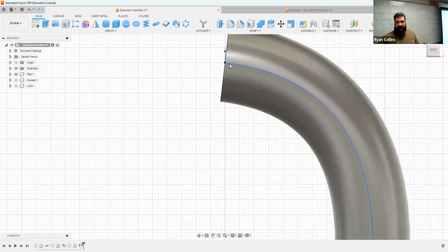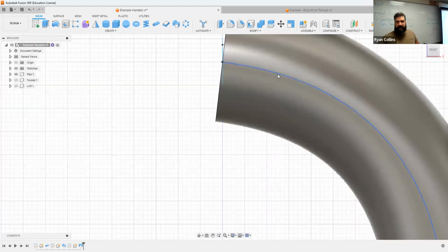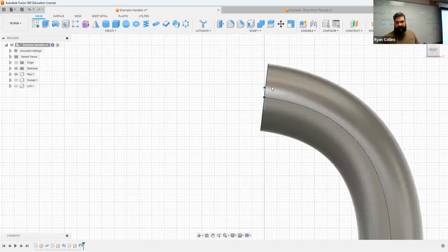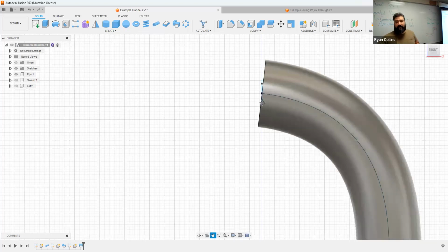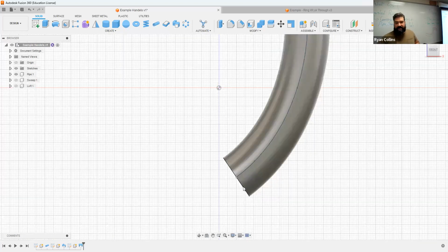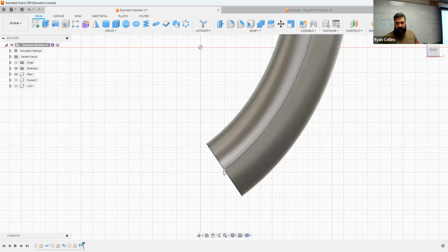So this sketch immediately curves downward. If I wanted it to stay flat, you would want to keep that sketch a little bit more straight and maybe add some more points along that fit point spline path. Same thing here. It's going to follow along, and it's just going to stop there relative to the curvature of the path. If you want a straight line, it would be a straight pipe. You can of course